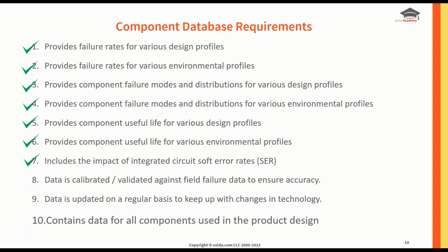Within the database then, another requirement is to look at the impact of integrated circuit soft error rates. So again, depending on the design and the application of your product, what altitude this product is going to be used at, and obviously then with things like smaller gate sizes and larger VLSI components, altitude is an impact. So you need your database to have the information there for that type of error rate.